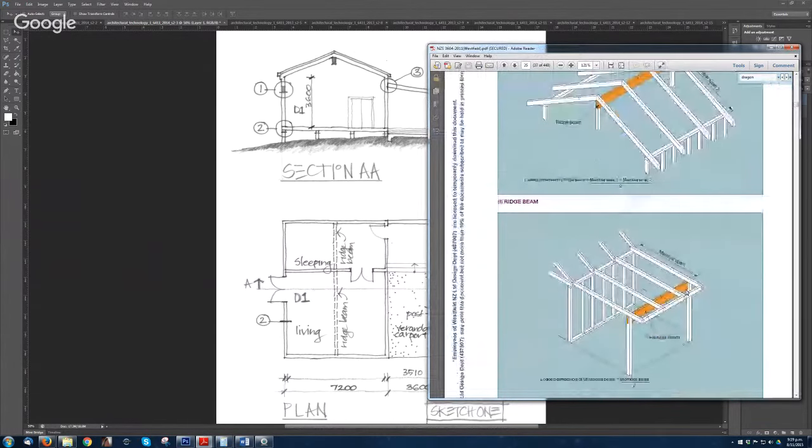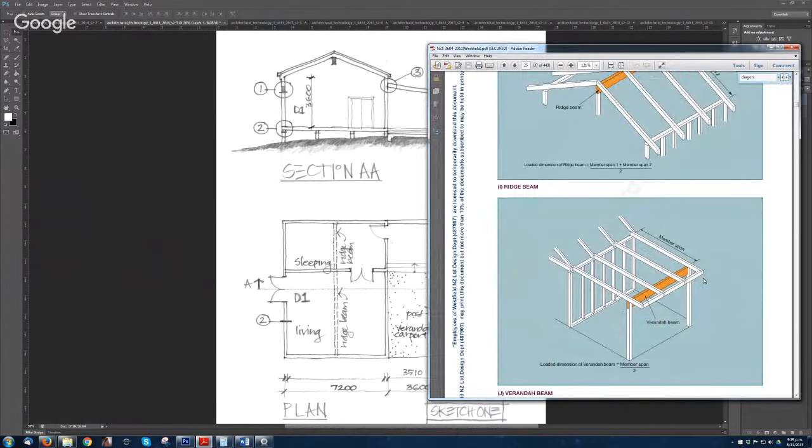That's there. So that shows you the sort of setup that you'll have, pretty close to what's in the exam. Same layout. But in the exam we have another post here. At the moment the span of that veranda beam is from here to there, because that's just between the two supporting posts. I'll show you where you've got the member span, and then dividing that by 2 for your order dimension.